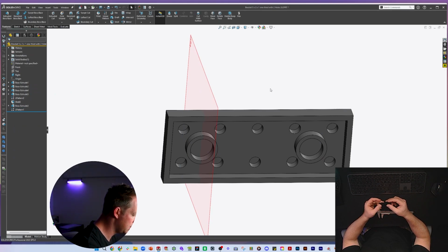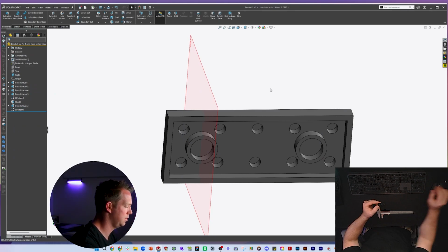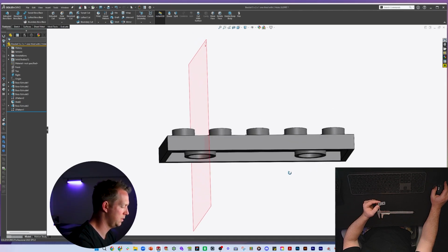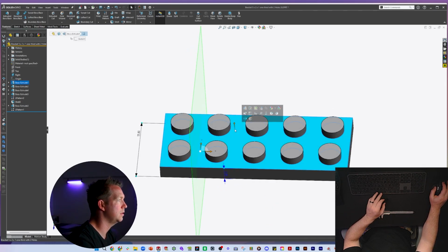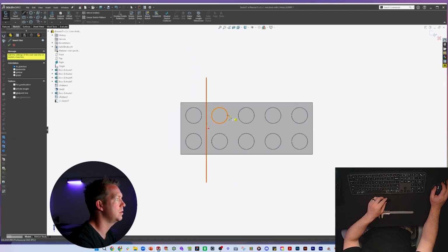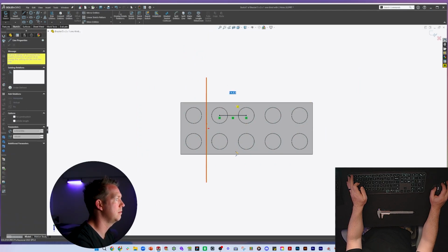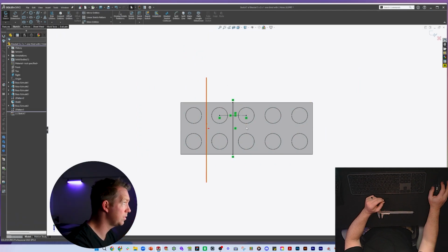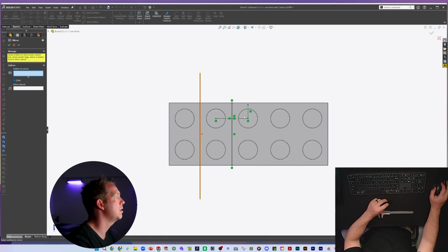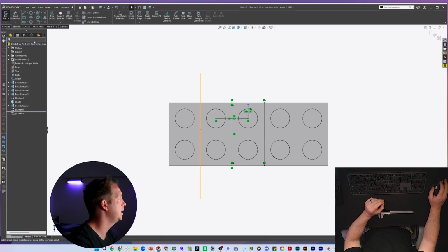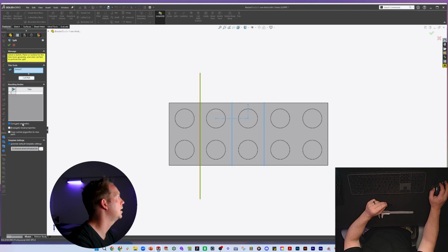And then I'm going to suggest we do a split feature. So what I'm going to do is find the midpoint between these two, which is going to be this line here. And at this point, there's actually 2 points we're going to do. This one, we're going to mirror this one around here. We're going to split this one solid body into 3, like so.